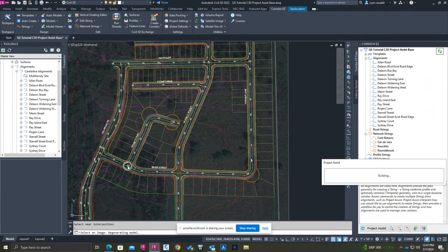If you look over in this intersection here, you'll notice that where that edge, the travelway line is, it's getting pulled into the center of the road, and that's creating that all crowned road. We're waiting for this other side to pop into the center of the road, but that should happen any moment. And then, yeah, that one's already starting to show up. And then you've got your cul-de-sacs. So the cul-de-sacs are getting built, and everything's in the order that you saw it in that workflow. So from top to bottom, alphabetically from your alignment naming convention, it's just going through the process and building it all out for you. There you go.